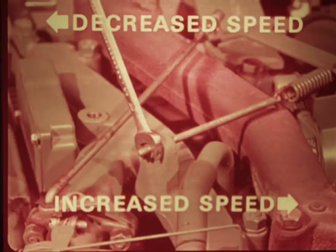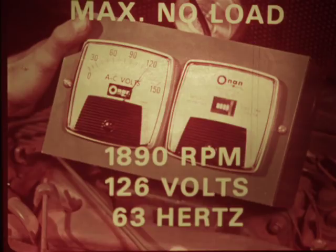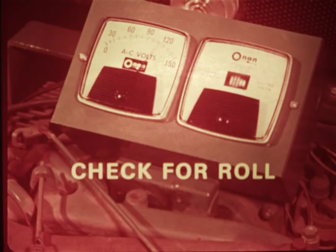Set the no-load speed at the governor spring adjusting nut. Loosen it to decrease speed or tighten it to increase speed. Adjust the nut for 63 hertz on the frequency meter. The maximum no-load speed is 1890 RPM, and the maximum no-load voltage is 126 volts. However, the frequency setting will be most accurate for proper generator output and is preferred to RPM or volts.